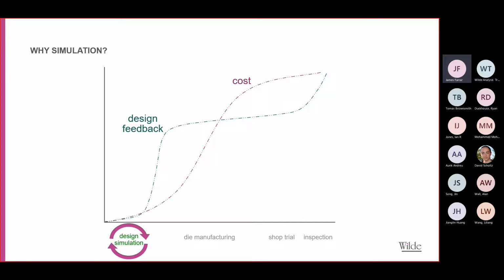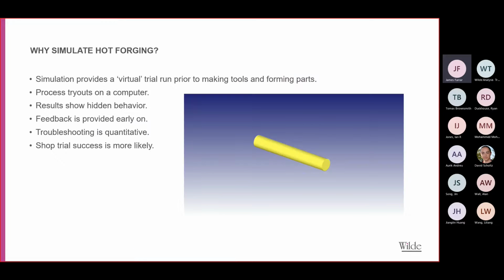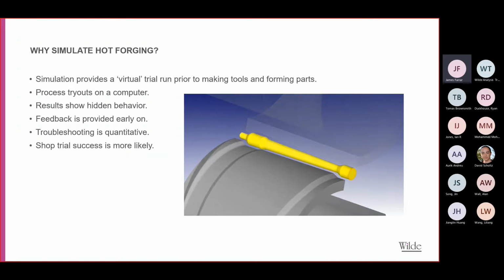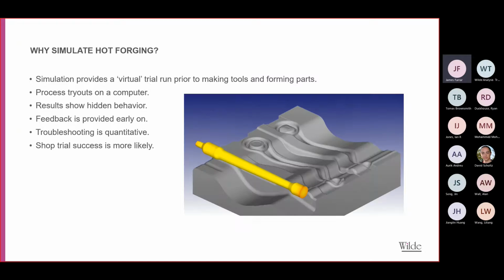So that's the overall vision of why simulation, one of the many benefits of simulation, in terms of upfront process design. It really gives you an option to try out these virtual trial runs prior to cutting any tools or forming any parts, so that you can understand how the material's flowing, where the material's going to move, what the loads are on the tooling, whether the tooling can withstand that, what kind of tooling design you need, and the material specs you'll need for those tools as well.